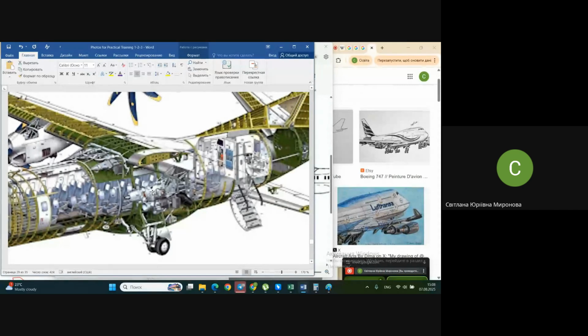You understand it? It's like you have two separate airplanes, one with cockpit and first passenger cabin, and another with a second passenger cabin, which does not communicate immediately. It's not possible to pass from the nose to the rear fuselage, for instance, during flight. Two separate cabins completely in this case. So mid-wing, neither for passenger airplane nor for cargo airplane, is usable, just because of these inner structures.